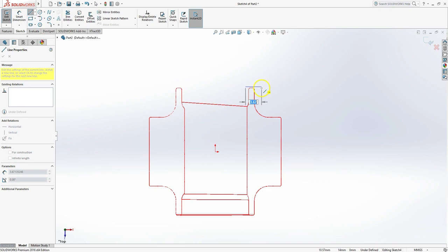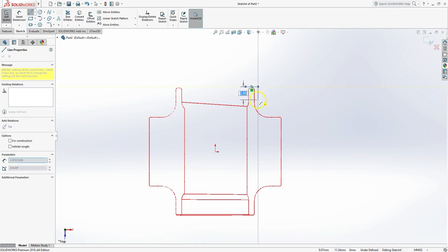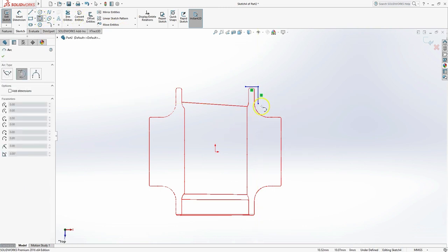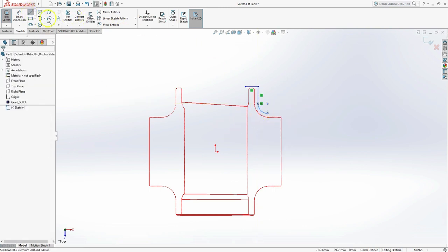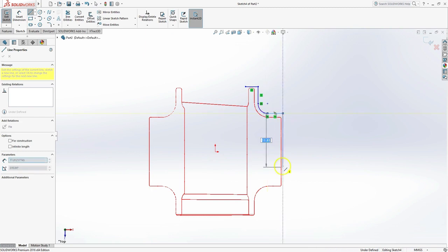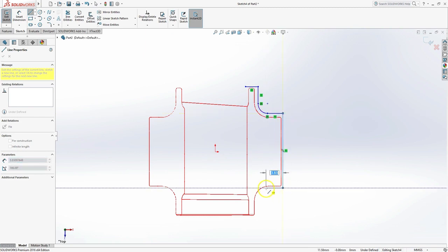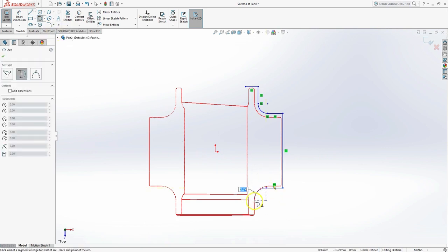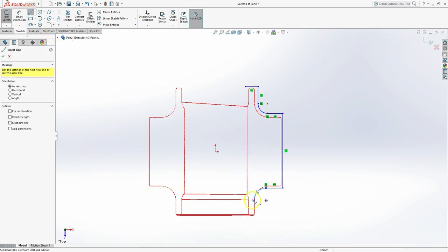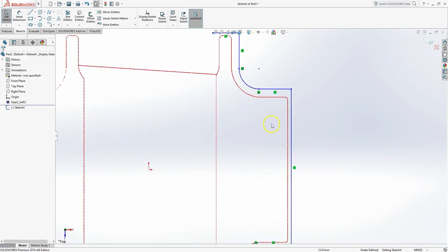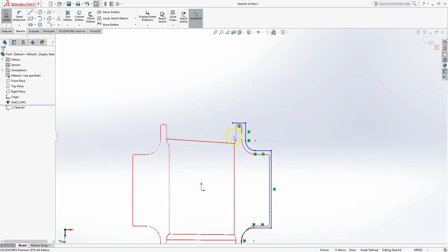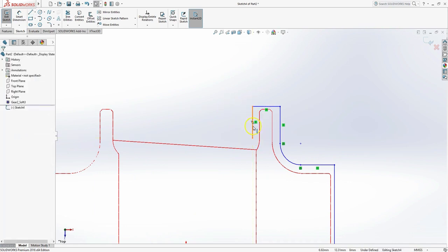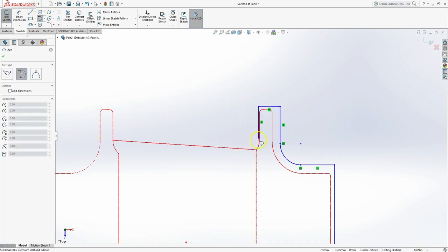So we're going to use our standard sketching functions in SOLIDWORKS to start drawing out all these features. Make a tangent line there, line, tangent arc there, and line straight down. Okay, I'm just sketching these roughly in the right position, and we'll go back and adjust those later. Actually, this one I'm going to get a little closer. So I'm going to do a tangent arc.